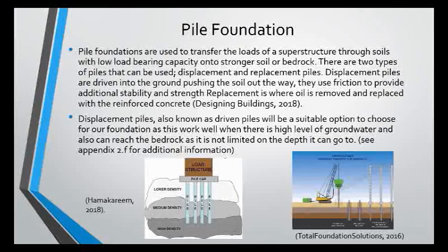Pile foundations transfer the load of the structure as far down as is required, using driven piles down to the bedrock. They use friction to provide additional support, as they are driven with no excavation and work well when there are high levels of groundwater.